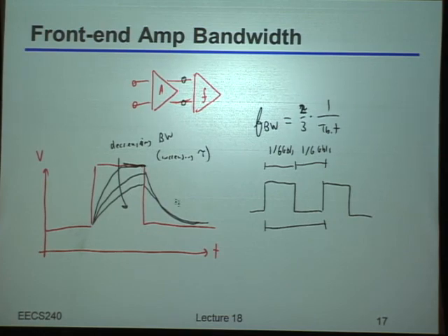But remember, there's always this long tail on the other side. So the problem is that if you just make your bandwidth very, very slow, but then up your gain, what will eventually happen is that you'll be remembering so many of the previous bits that you really just have no chance of crossing the threshold. Okay? If, for example, all of the previous bits were the opposite of what your bit should be.